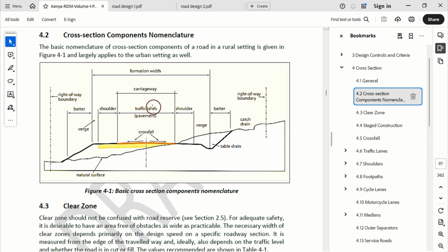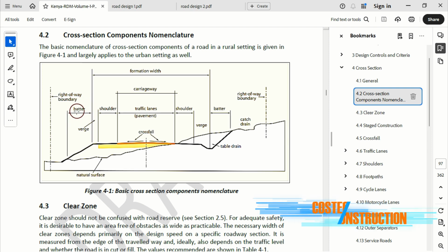Our sub-assemblies parameters will be from this road manual. After defining the right and left shoulders, we'll add a VERGE, then conditional cut or fill daylights to have the assembly linked to the existing ground surface. At the cut areas, we'll utilize a side drain that will prevent stormwater getting to the road. The end condition for the fill areas will be as seen in the left and cut at the right side.